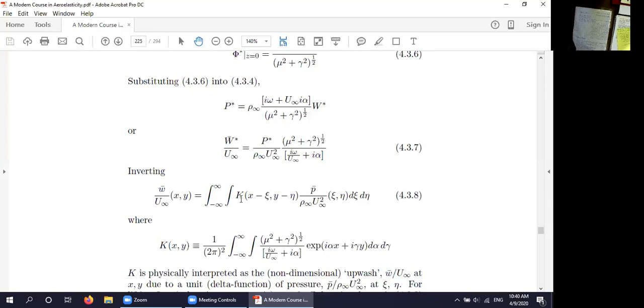It's a subtle reason why it doesn't work. It turns out in subsonic flow, although this is usually mentioned in a course on aerodynamics, the solution of this equation is not unique. There's a whole family, an infinite family of solutions. And so you have to apply some additional constraint on the equation to get a unique and physically meaningful answer. And what people usually apply is the Kutta condition, which, if you've taken a course in steady flow and subsonic aerodynamics, you recall requires the pressure to be zero at the trailing edge. That's an empiricism.